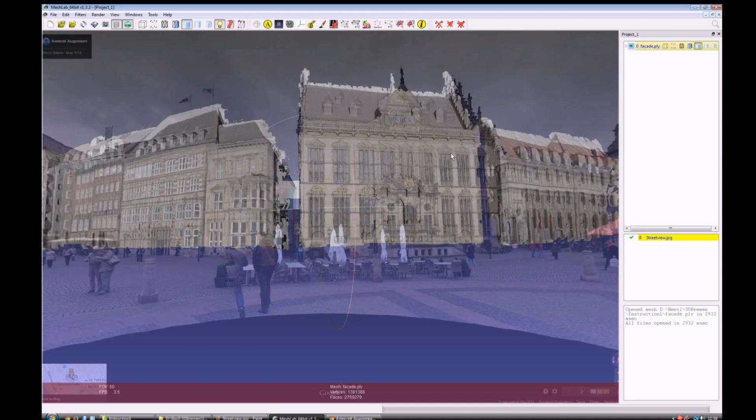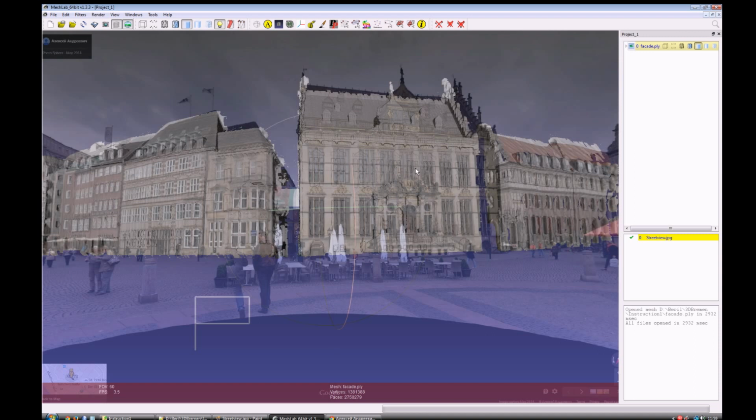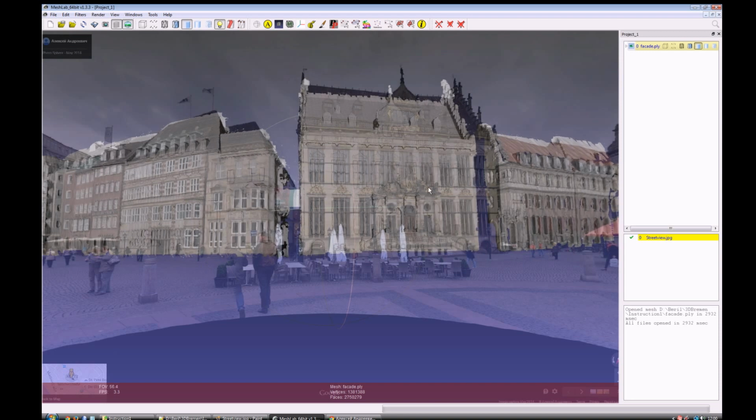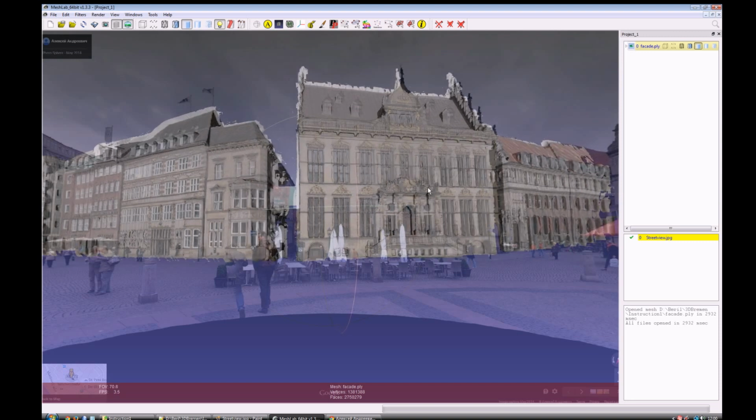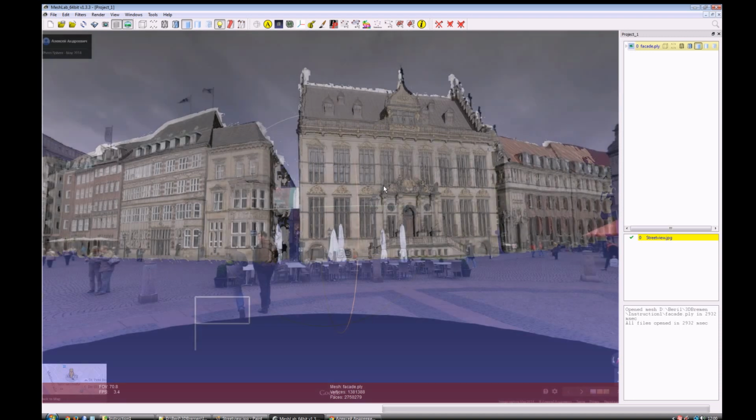And this is going to take a while because it requires me to change position and orientation, but also I need to change the focal length to adapt it. In the lower left corner you can see here FOV 60, and this corresponds to the field of view, which depends on the focal length, and I can change this by using the Shift key and then scrolling the mouse wheel, and then you can see the shape of the buildings change. So I can get a closer match by adjusting this. Okay. So now we're getting pretty close already.